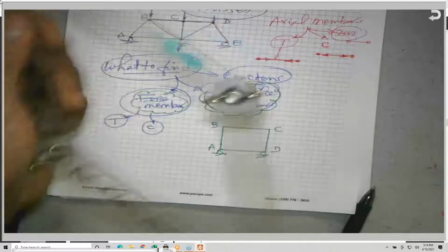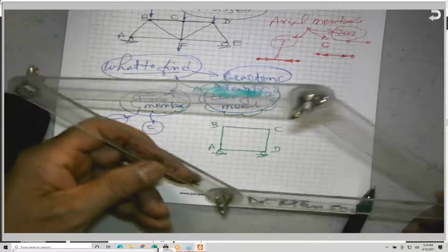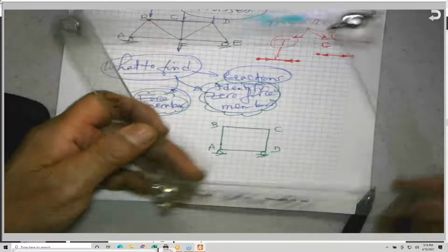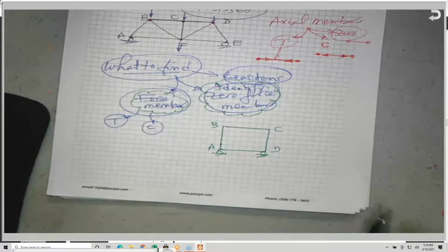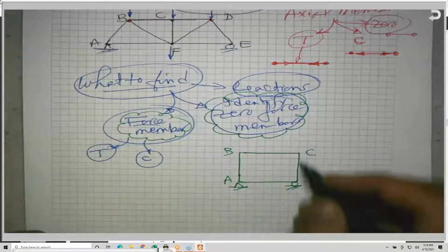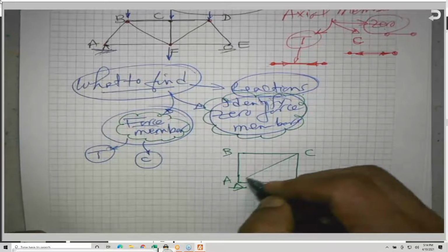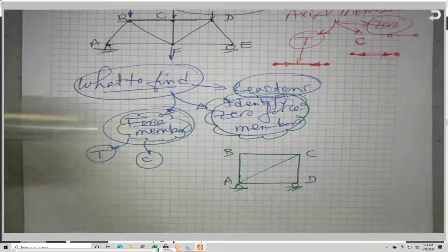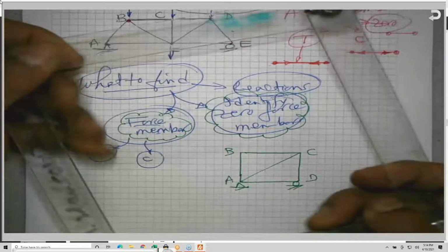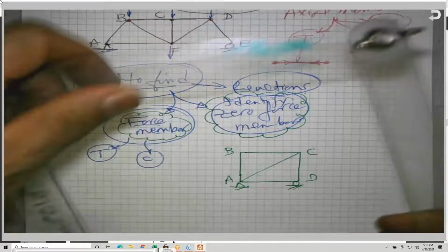It can do this. Have you ever seen a truss doing this? I would be in big trouble if I designed a truss like this, because this is not a truss. This is called a mechanism. I told you the basic unit for any truss on Earth must be a triangular shape. So in order to make this mechanism into a truss, I have to add another member. Now it became a truss. If I added another member, connecting this to this, you will find it became stable.